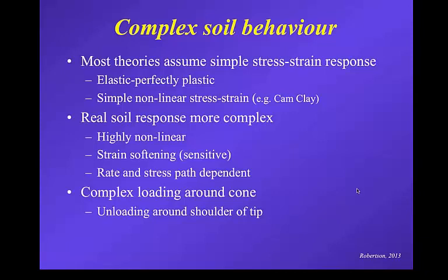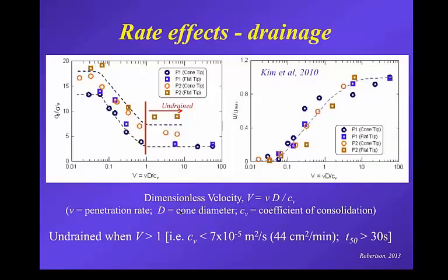It's a big issue when you measure the pore pressure on the face because, of course, it's dominated by this normal stress from the tip being applied to the soil. Less of a problem at the U2 location, but sometimes you can still see it in certain types of soil. And so the general recommendation is to clamp the rods to minimize that sudden drop from unloading. You'll see in the subsequent ones I show, we typically clamp the rods during a dissipation test, and so you'll see that we don't suffer that problem.